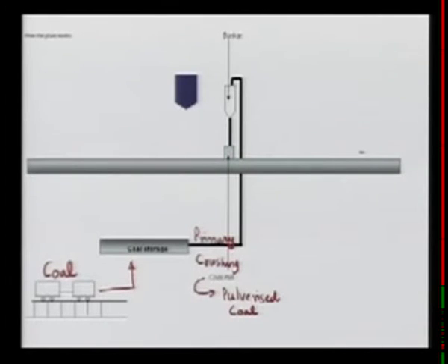And how it happens is that the outlet from the coal mill goes to the boiler, or this little firing area that you see. Apart from the coal, air is supplied, and the pulverized coal burns very well, giving you high temperature, high energy. And then what we do with this energy is to have a system of water tubes. You can't see really very clearly here, but you can see the tubes which are filled with water, and the heat that is generated from the boiler heats the tubes, which we all know. It's a kind of water tube boiler.